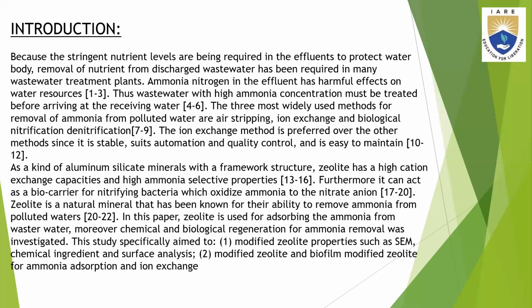As a kind of aluminum silicate mineral with a framework structure, zeolite has a high cation exchange capacity and high ammonia selective properties. Furthermore, it can act as a biocarrier for nitrification bacteria, which oxidize ammonia to the nitrate anion. Zeolite is a natural mineral that has been known for its ability to remove ammonia from polluted waters. In this work, zeolite is used for adsorption of ammonia from wastewater.